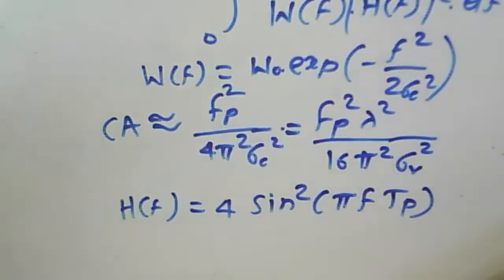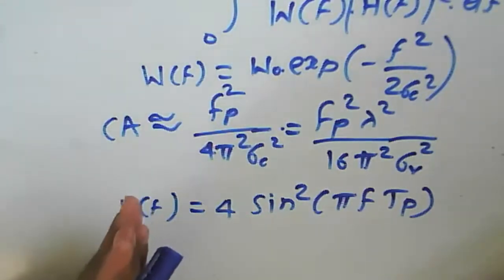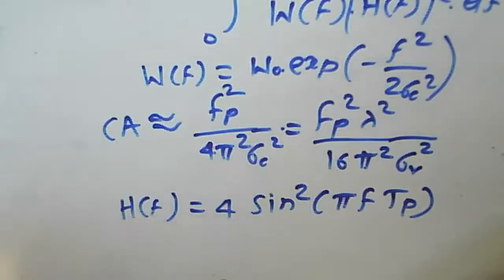Instead of a single delay line canceller we can use a double delay line canceller, which, for clutter with this frequency spectrum, will attenuate more of the clutter.